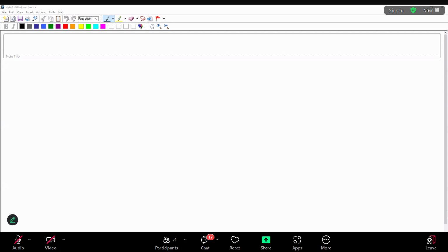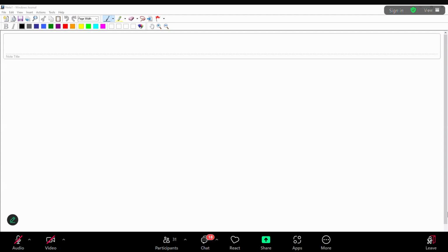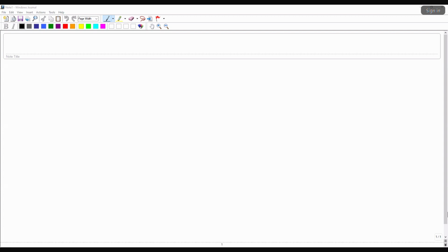Intrusive methods are those where you put in an instrument to measure something, but in the process of measuring, you also perturb the original measurement field. So you need to know how much you need to correct your data, if that is something that is systematic. But with non-intrusive methods, typically the perturbation that you introduce into the field by putting in the instrument is negligible. So you may not need any correction in that case.